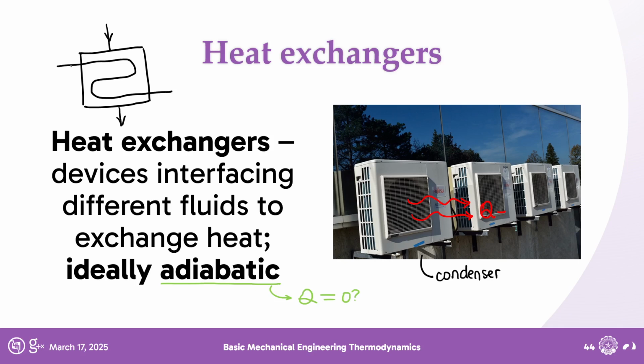For example, we have here a condenser. This is a figure, a symbol for the condenser. Sino ba yung mainit? Who is the one rejecting the heat? Well, condensers use refrigerants, refrigerant 22, refrigerant 134A. There are way more in the market these days. But basically, flowing in here is the refrigerant.